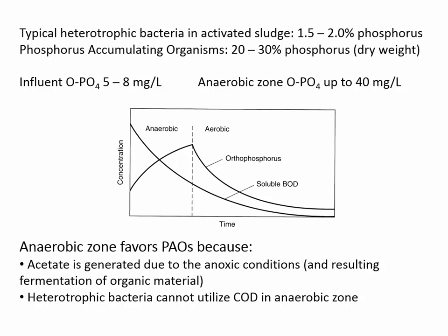And so, like, mass cannot be created or destroyed. So the same mass of phosphorus is inside the aeration basin at all times. There's the same overall mass. It's just converting it from one form to another. It's converting it from ortho to poly.